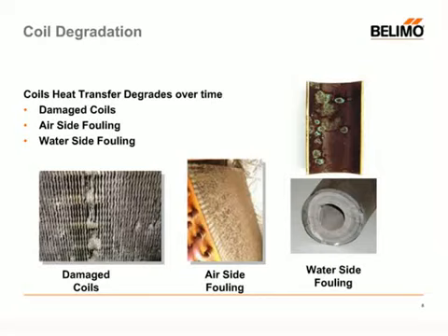Systems improperly balanced is another common cause of low delta T. The systems become out of whack, and they need to be balanced from time to time. Non-dynamic balancing is another common cause, which would be basically if a system was not using pressure-independent valves, using regular pressure-dependent valves. So there's a whole host of other items that cause low delta T, and we're not going to go into all those in detail today.